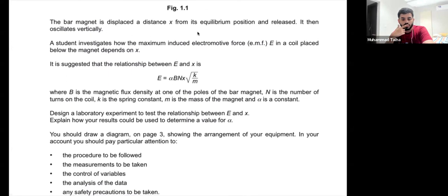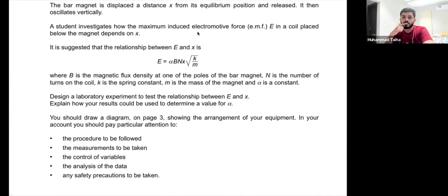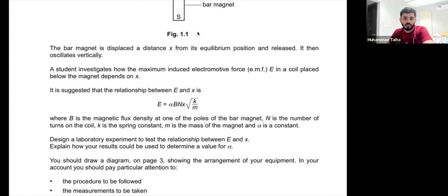What else? Yeah, so that's what we have to measure, the max induced EMF. It's not just the induced EMF, it's max, and for good reason. This is because this voltage reading is going to fluctuate. That's what it means. So my instrument of choice here would be an oscilloscope, right? And also, if the examiner in this case was also accepting answers as voltmeter, a voltmeter would also work. I would still write an oscilloscope.